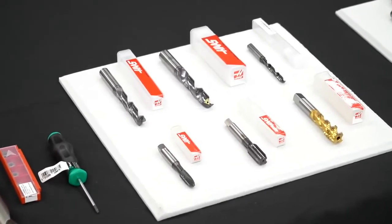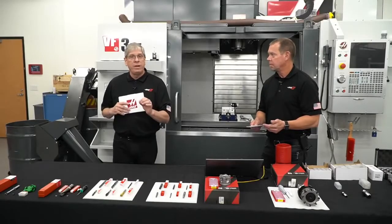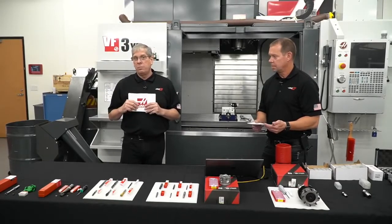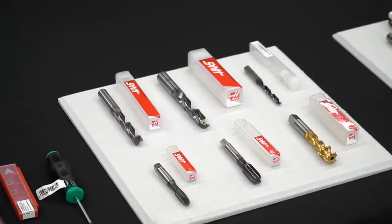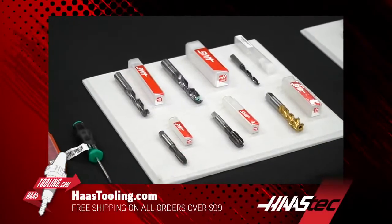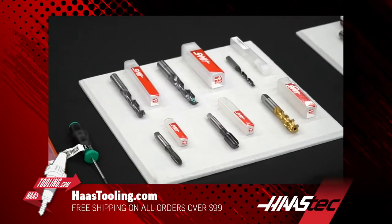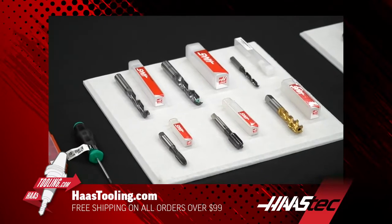Now the drill for stainless and high temp alloys is only available in through spindle coolant because those applications really require coolant down in the cutting zone. The drills for steel and cast iron, you can get in non-TSC and TSC versions. They're a lot more resistant to heat in those materials, so you don't necessarily need to use through spindle coolant on those carbide drills for that material.